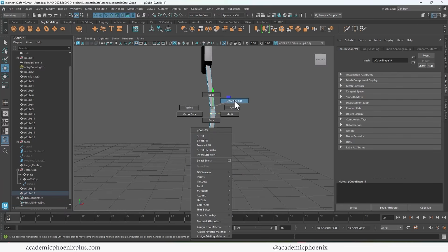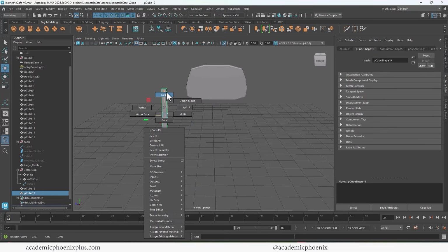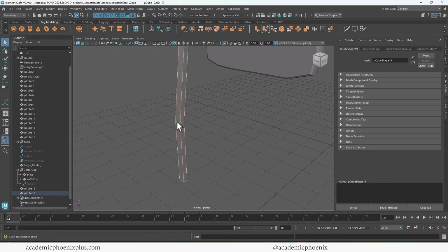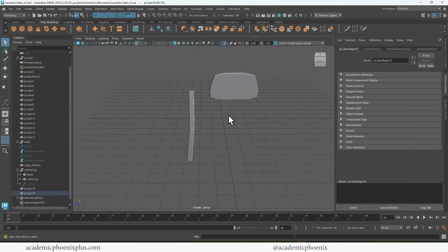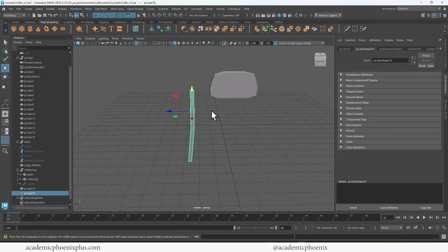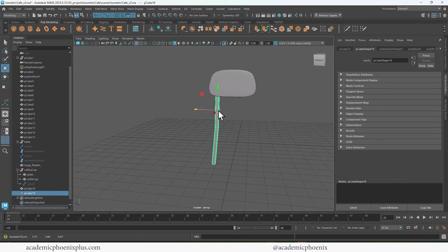So, as always, I like to make sure we have some supporting edges. Let's go ahead and move this to the sides. Let's go to edges, select everything, and then Control double click and do a Control B, which is bevel, increase your segments. Looks pretty good. Let's go ahead and put it back. Let's press 3 on this one so we can see what it looks like smooth.